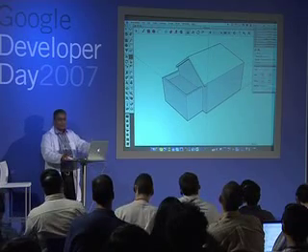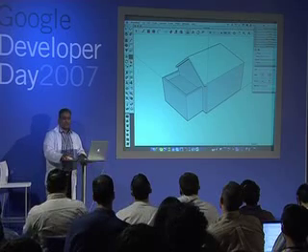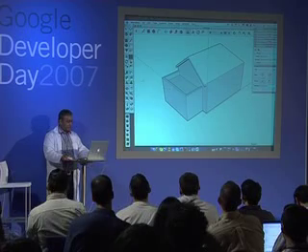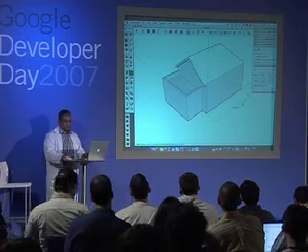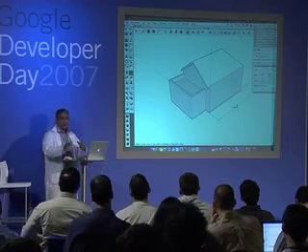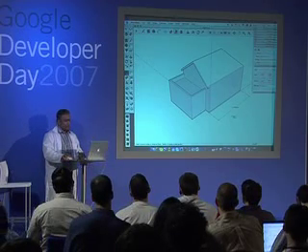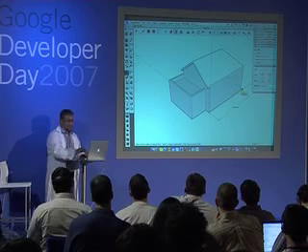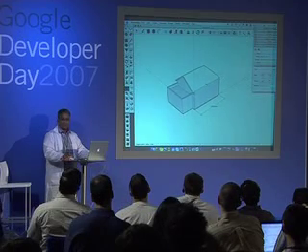All of these tools, you could program a shortcut on your keyboard. So you don't have to keep on going and selecting the icons. M for move, L for line, and so on. Okay. I'm just going to put a dimension on this building. It's actually 21.9 meters long. I want my house now to be 15 meters accurately. So I'll use my tape measure, and I will just measure from that point to that point and type in 15 meters. Okay. I have a house which is now 1:1.